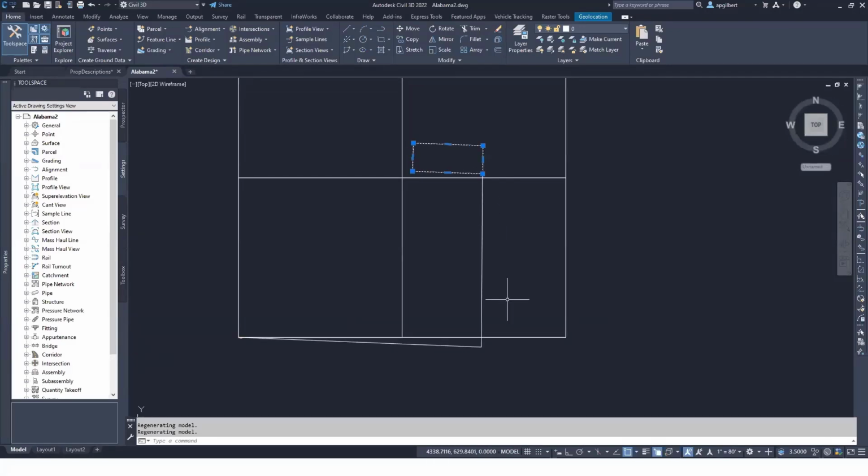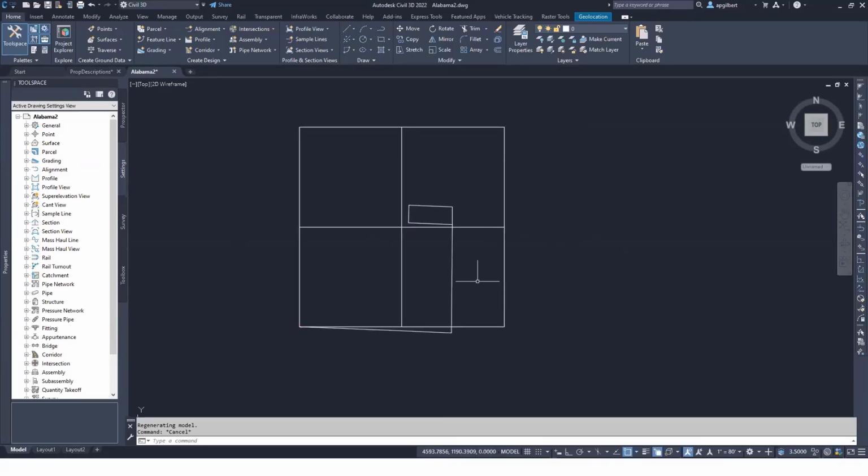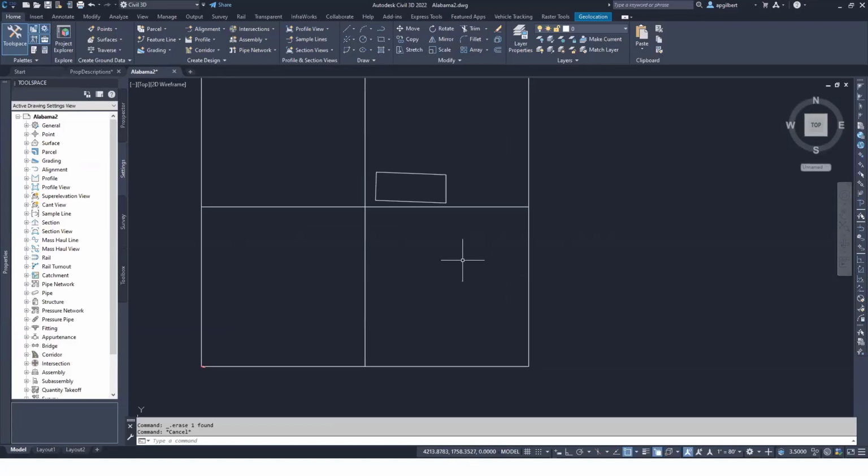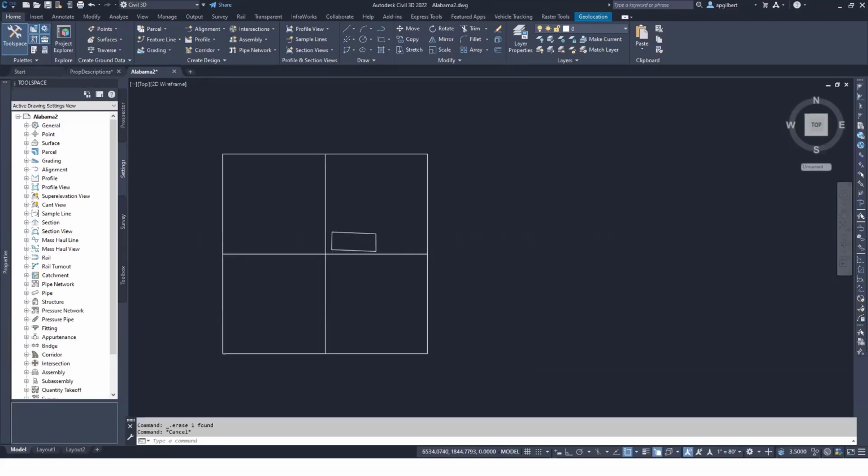So we have a rotation issue, right? What I'm trying to do here is take this data up to state plane, so I'm trying to transform it into my state plane coordinate system. Normally I would go monument to monument and all that, but we're going to freehand it here just to show you an example of what you can do. Before that, I'm going to delete the Polyline for the commencing calls because it has no tie back to the Traverse. It's just a line.